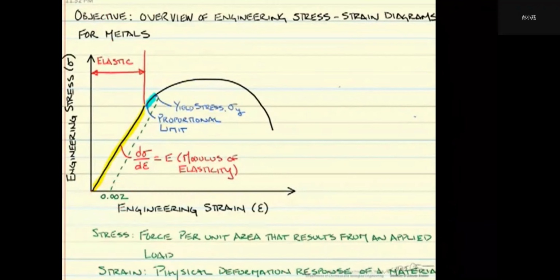Note, since there is a degree of elastic recovery, we do not draw the unload line straight down. We draw it parallel to the elastic curve. One thing to also realize is at a microscopic level, we have dislocation motion and permanent deformation that has occurred. That is why we are now in what we would call our plastic region.